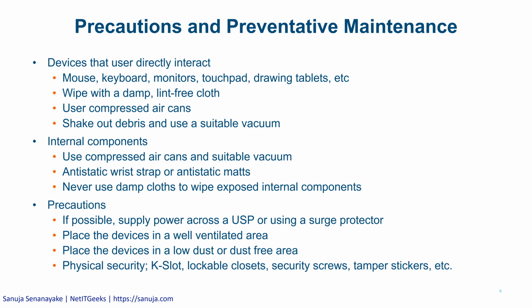Anti-static mats are not very common. I have one at home. Those are large mats with a wire in the corner where you plug it into a ground, either by putting that wire onto your desktop machine itself, or in most cases with these anti-static mats, we just plug it into the ground wire of any electrical circuit. So that mat is basically grounded. Now you can stand on top of that mat knowing that most likely the static electricity will be dissipated. Those are called anti-static mats.